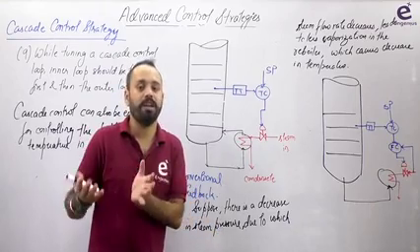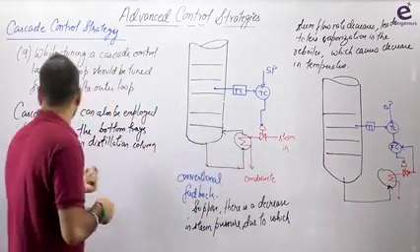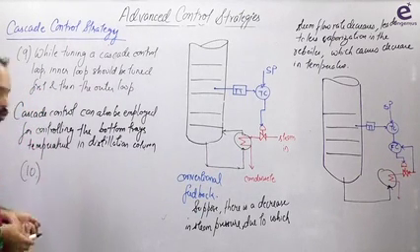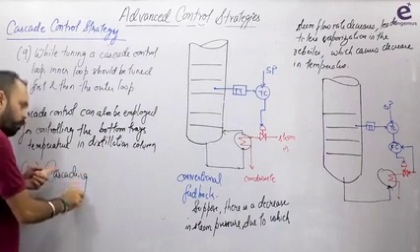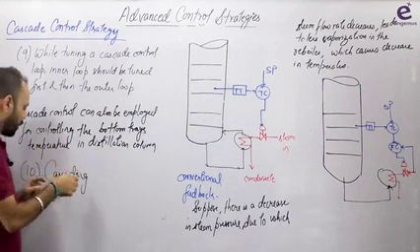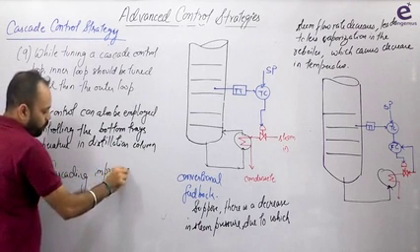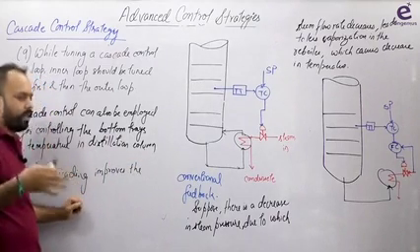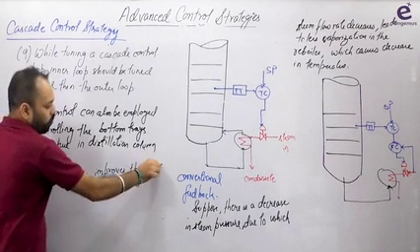मैंने आपको बस पूछा ना, when cascade should be applied, how cascade should be applied, right? And what cascading does actually, पता भी होना चाहिए. आप बोलोगे कि नहीं सर, आपको पता होना चाहिए कैस्केड करने से होगा क्या. Cascading, provided that the requirement that the secondary controller is faster is met, only then this will happen. Cascading improves the overall response. बस improve कर रहा है. तो आप बोलो सर improvement जरूरी है क्या? जरूरी है कि नहीं है, that totally depends upon you. Cascading improves the overall response.